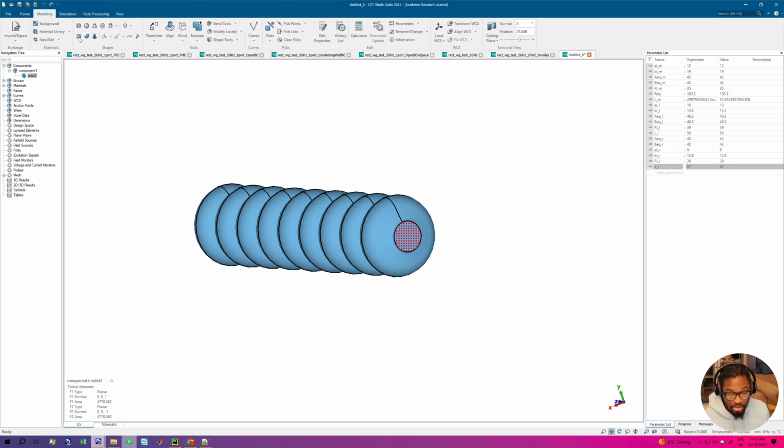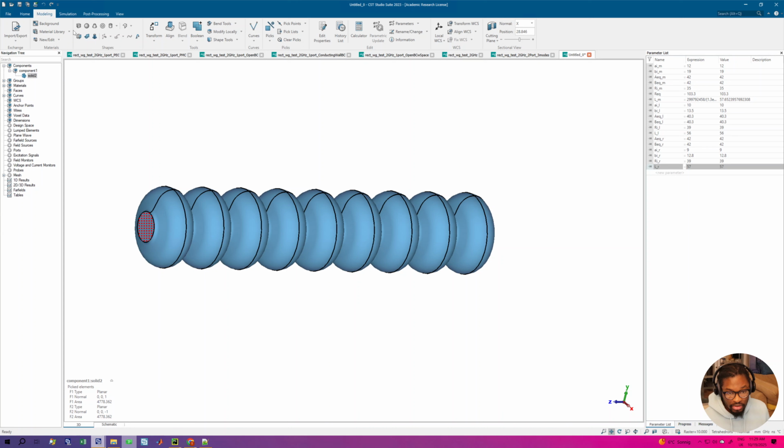Why is it not showing on hover? Is this button here? That's the extrude button. And so I want to extrude face, and the height, you could give it any height, but I usually use 4 times the mid cell length. I think 4 is too long, so I'll use 3 times the mid cell length here. And I preview it.